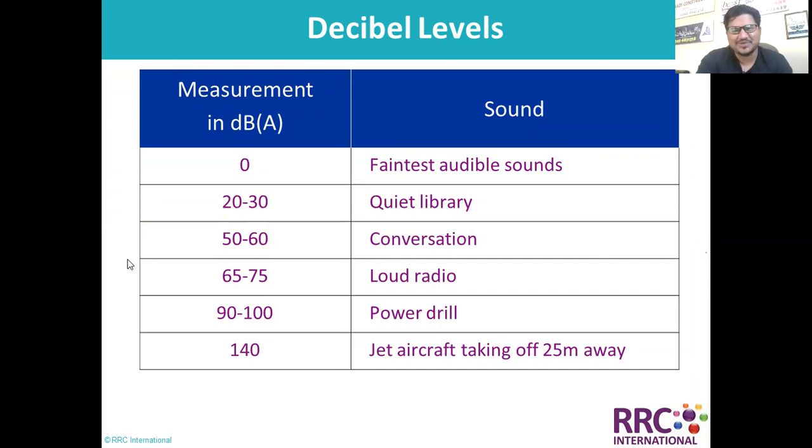And later on, he won the case because the company couldn't prove that they were taking care every day and that they provided the right set of PPEs, especially earplugs and earmuffs. They couldn't prove it, because the noise level was above 110 decibel, and they were providing earplugs or earmuffs which could reduce only 10 decibel. So it was still above the legal limit. Also, whenever they issued the PPEs, they didn't retain the records for the last 10 years, because the retention period in their documentation was just a maximum of 3 years. So 7 years of records were already shredded. And he won the case, and millions of dollars in fine and compensation was paid to that gentleman.